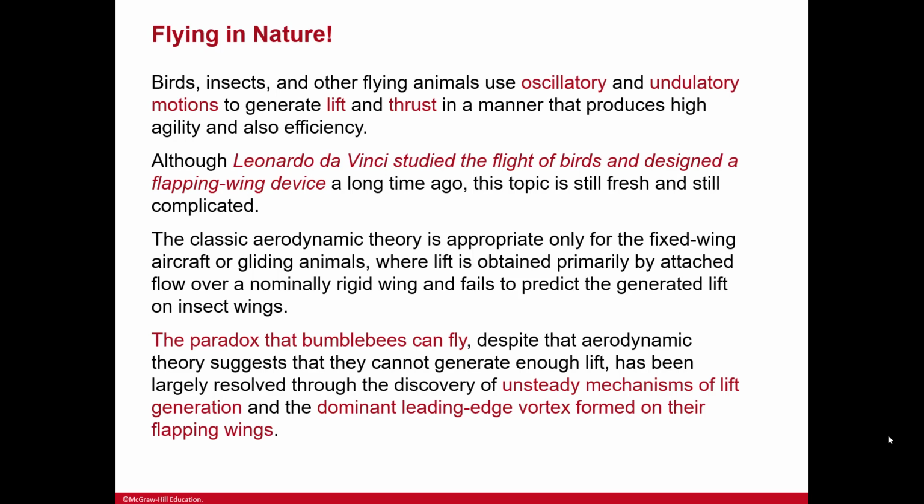The paradox that bumblebees can fly, despite the aerodynamic theory suggesting that they cannot generate enough lift, and clearly they can, has been largely resolved through the discovery of unsteady mechanisms of lift generation and the dominant leading edge vortex formed on their flapping wings.